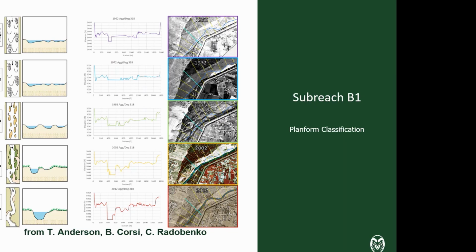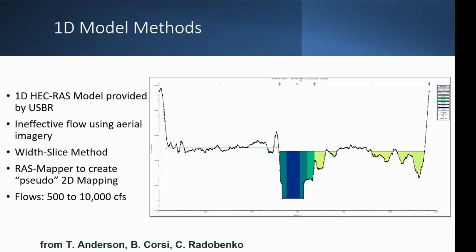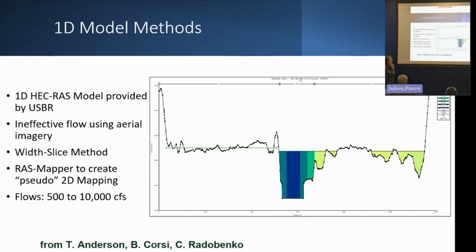So this kind of work we're doing, and we used HEC-RAS. And 1D, essentially, we had to work on how many slices will I have, how many slices do you want to have within the channel versus the floodplain.